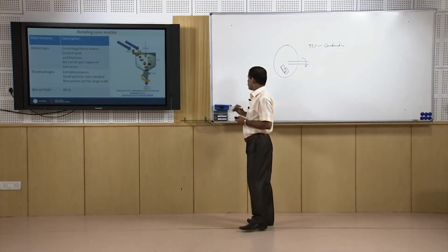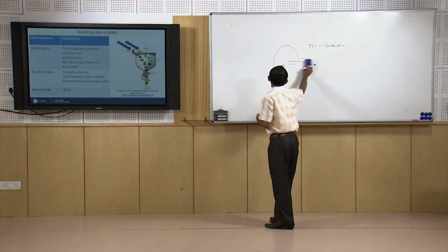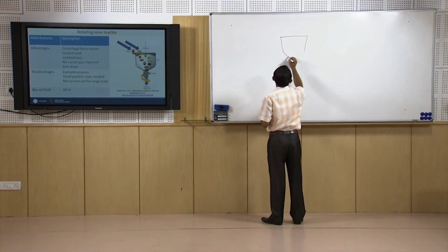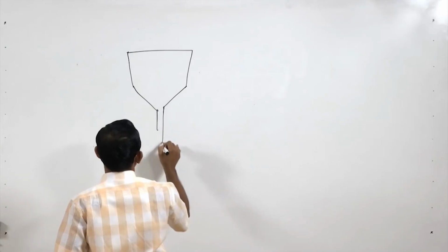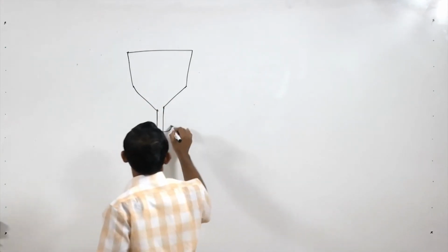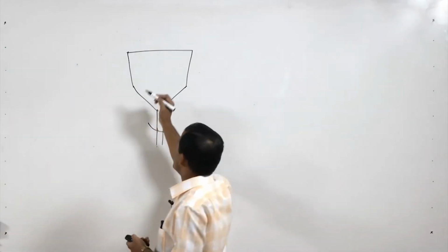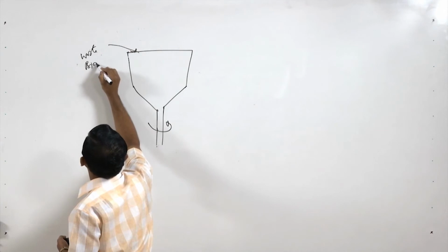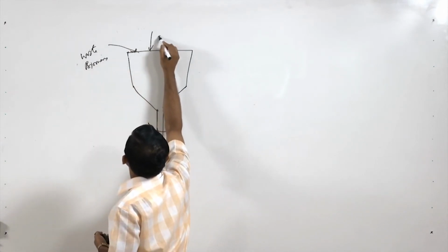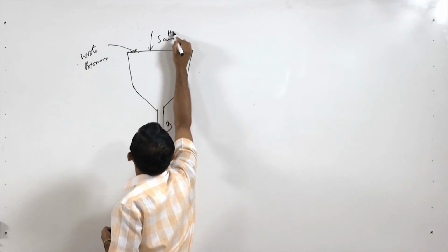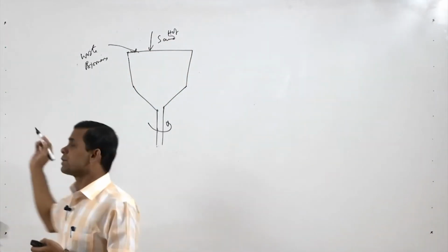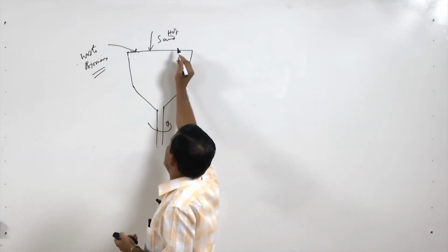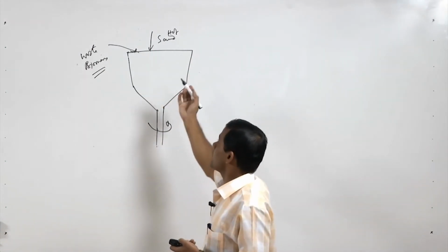Next we will come to the rotating cone reactor. In the rotating cone reactor, one cone shaped reactor is used. This cone shaped reactor is rotated and we add waste or biomass from the top and also hot sand. There is some centrifugal action on it, so the waste biomass and hot sand get mixed. So, heat transfer is very fast.